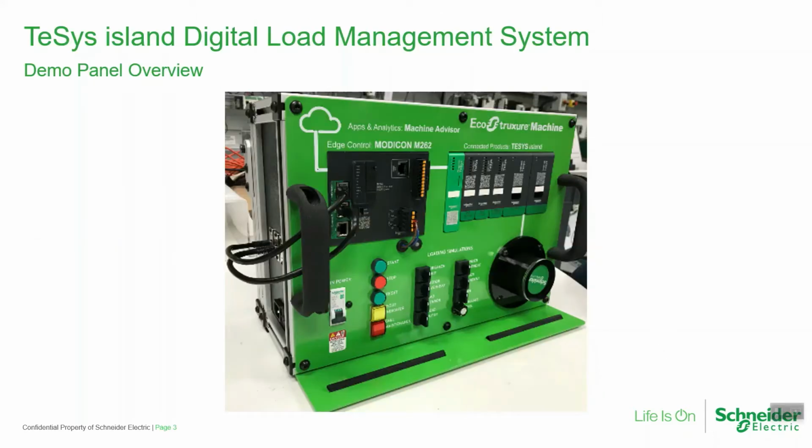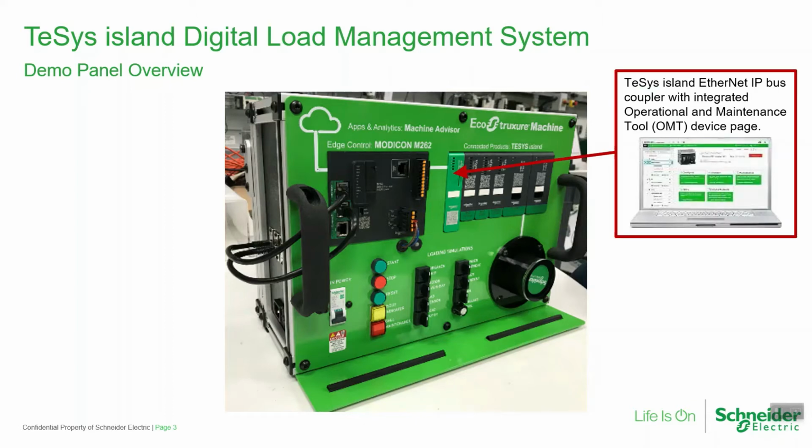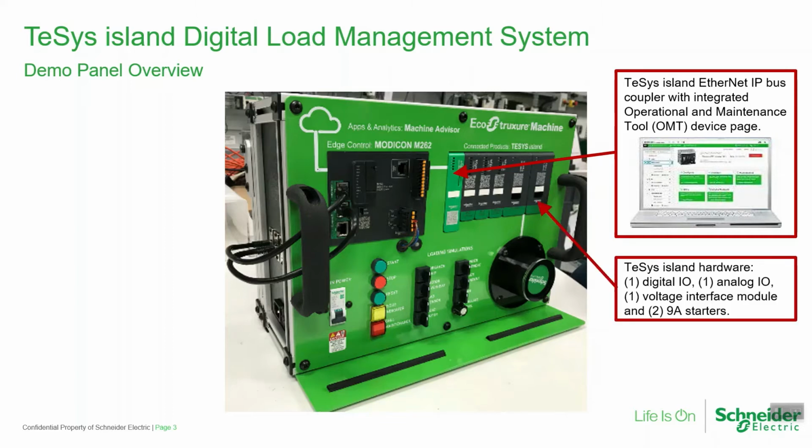The TeSys Island Digital Load Management System demo panel that we'll be using today is pictured on the screen. The demo panel includes a TeSys Island Ethernet IP bus coupler with an integrated operation and maintenance tool. We'll connect our laptop to the bus coupler and we'll be able to adjust the parameters for the devices in the island that are stored inside the bus coupler itself. The TeSys Island hardware includes one digital I/O, one analog I/O, one voltage interface module, and two 9-amp starters.